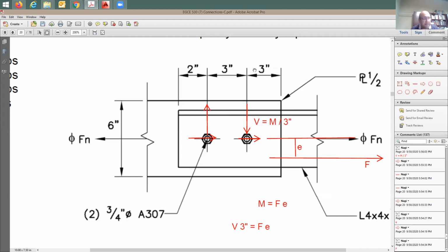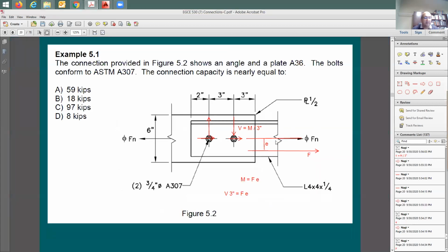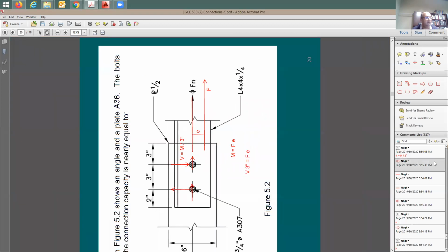Any questions on this concept? When you have some eccentricity on the bolt from the force? Certainly you can take the whole assembly here and rotate it 90 degrees, right? So if I'd like to take just this piece here and rotate it 90 degrees, what do I mean by rotate this 90 degrees? Let's say, do it this way. Same concept applies, right? So if you have a couple of bolts or 3, 4 bolts, and the force is going to be eccentric from the central bolts, you're going to have here some additional moment that you apply to the bolts.